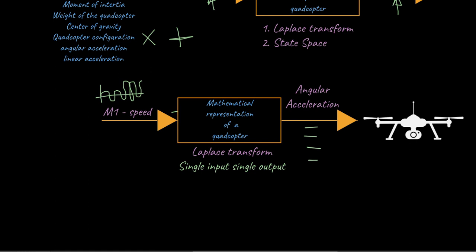You might want to change the diameter of the propeller. You might want to have a 2-blade propeller versus a 1-blade propeller. Because the propeller is the one that is converting the rotational force into an actual flying object, the propeller design really makes a huge difference, because the quadcopter equation wouldn't make any sense without accounting for how the propeller works. And that includes the material of the propeller. When it rotates quickly, how much vibration does it generate?